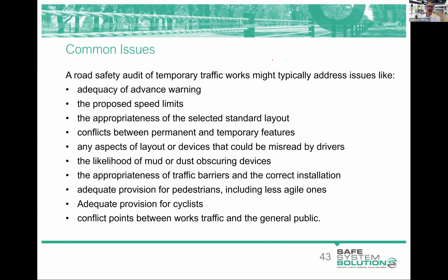You think about the appropriateness of the speed limits proposed. Standard layouts. I really do caution this because temporary traffic management and traffic guidance schemes can get a little bit like a sausage factory where they just churn out these things. And have people thought about them in detail around the context of the environment they're being deployed in and the appropriateness of the off-the-shelf design? It happens less with actual road design, that they're just sort of running with a standard layout.